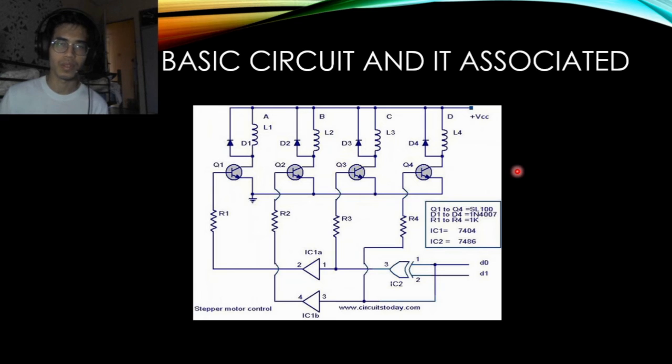So this diagram is the basic circuit of the stepper motor controller. The driver circuit uses 4 transistors here, SL100, to drive a motor winding. There are two NOT gates and one XOR gate to decode the 2-bit control logic to drive the 4 windings of the motor.